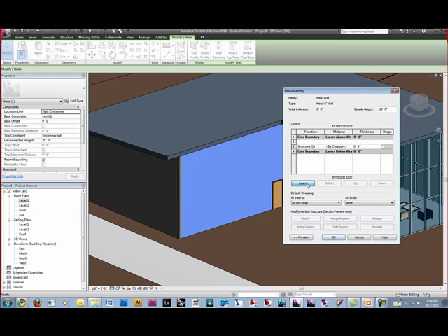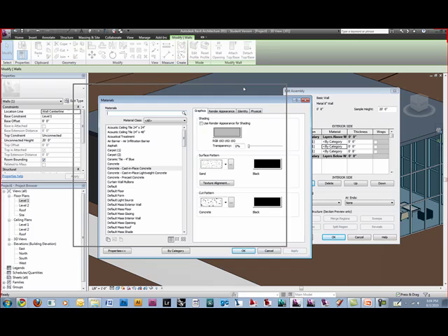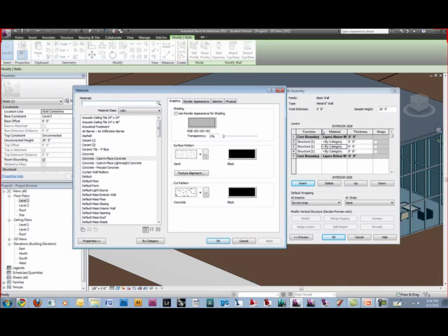What I'm going to do is insert two things. I'm going to have a core, which I'm going to call structure. Just leave it like that. The next button is actually where the materials are, and this is going to be the main mass of my wall. So maybe this is wood, or a stud layer or something like that. So in the materials I'm just going to tell it to be wood.